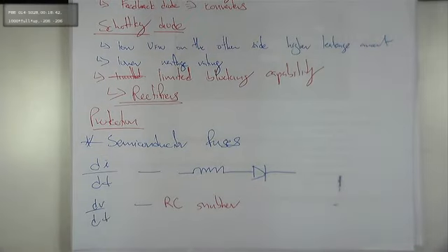Yes, you have heard of it. You designed one last semester, in E321, to protect your diode. In MATLAB there is a section where you have to fill in your RC snubber values. Yes, okay. This is the protection against dV over dt.